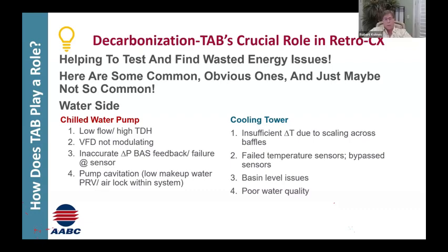Which is why we have the triple duty valve. We adjust that and put back pressure onto that pump. As a TAB professional, we would bring it back to the TAB position and mark the valve, because some contractors, controllers, or owners want to have the full capacity of the VFD. So we'd mark the balance position and then open it back up and allow the variable frequency drive to control to the DP out there in the system.